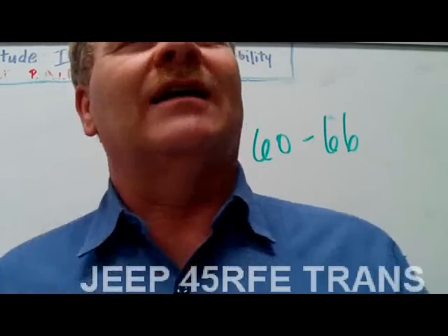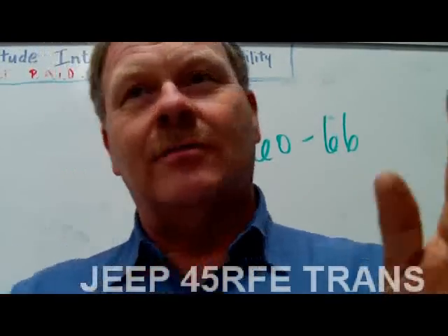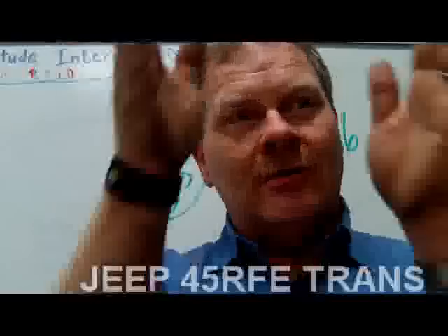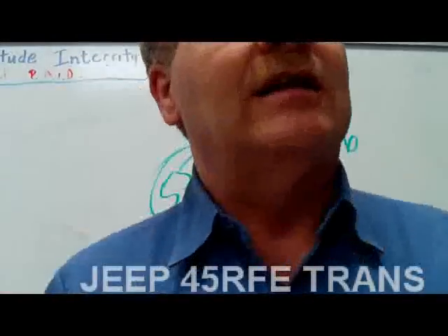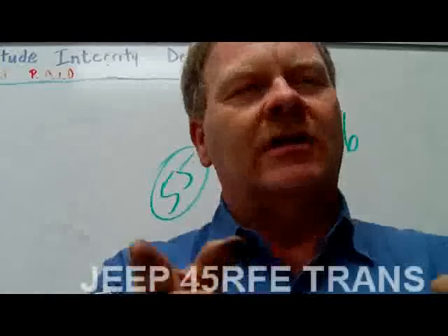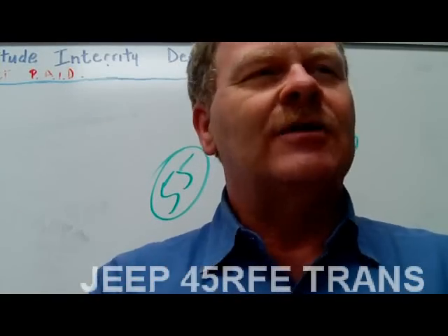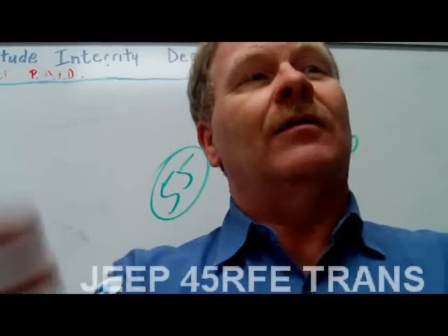So what do we do? We take a cooler that you buy from the parts house, which is a bunch of tubes that are snaked through some fins, and it's got two outlets, an inlet and outlet on it. We unhooked the hoses from the transmission cooler, ran them to this, and we put it outside.